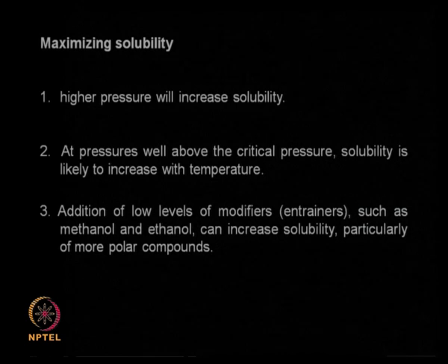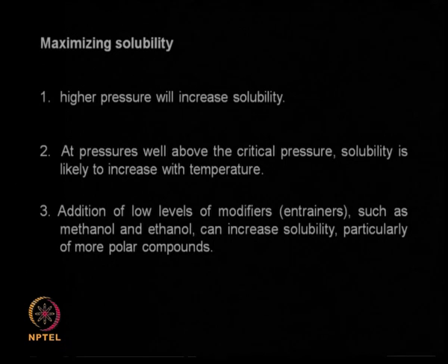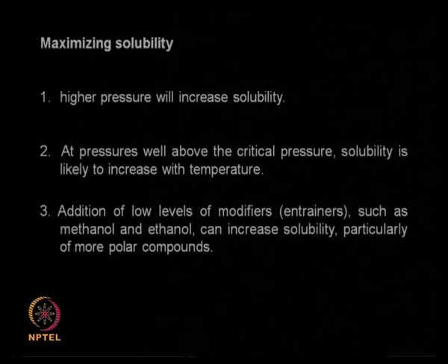How do you maximize solubility? We can use higher pressure. When you use a higher pressure, solubility increases. At pressures well above critical pressure, solubility is likely to increase with temperature also. So if you are using very high pressure, then the supercritical CO2 temperature also may be very high, so you may have to put in a cooling system to cool the supercritical fluid.